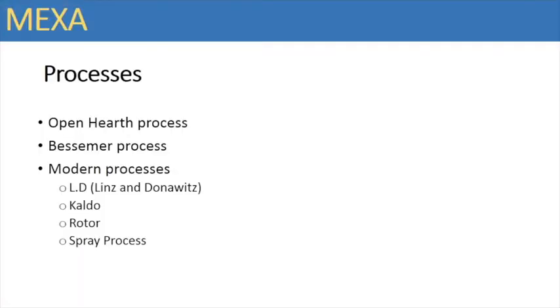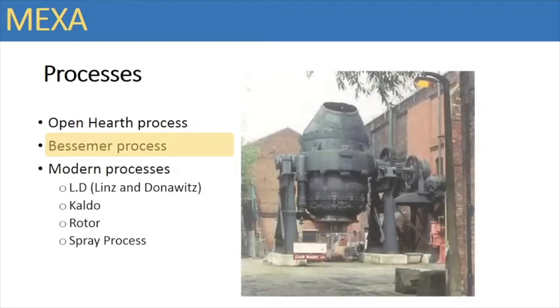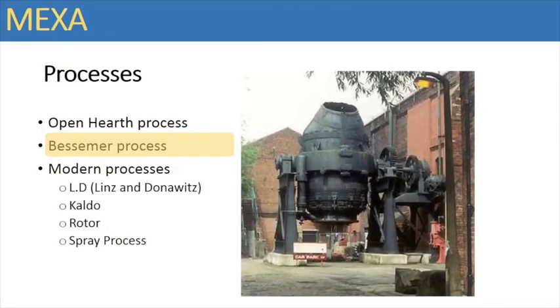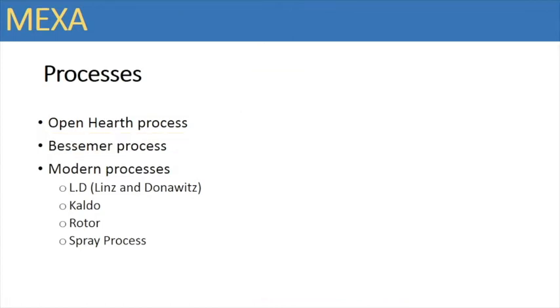Bessemer process. In this steel making process, a blast of air is blown through a charge of molten pig iron contained in a Bessemer converter. The principal difference between open hearth and Bessemer steels of similar carbon content is brought about by the higher nitrogen content in Bessemer steel, and is also partly due to the higher degree of oxidation with this process.